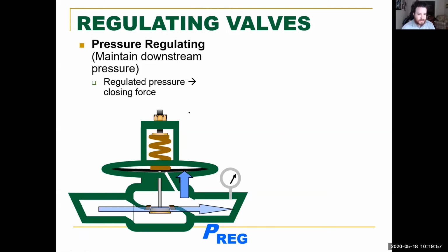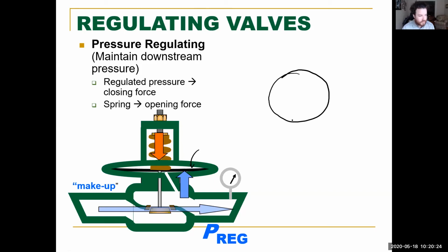So the regulating pressure is the closing force here. And the spring is the opening force. And the way that's working here is you have like this baffle material right there. It's like a piece of rubber. And the piece of rubber is going to be sealed on the outside edge.